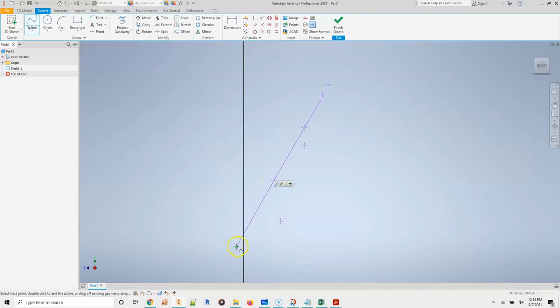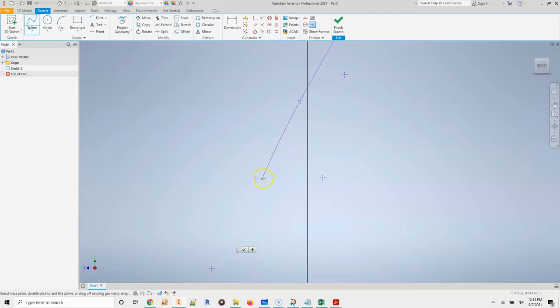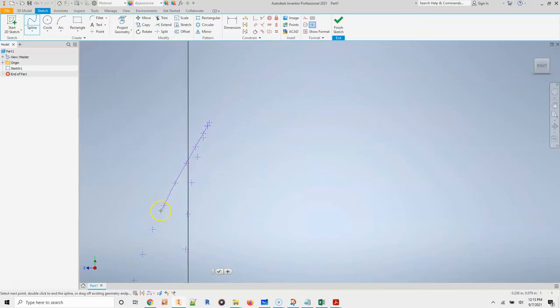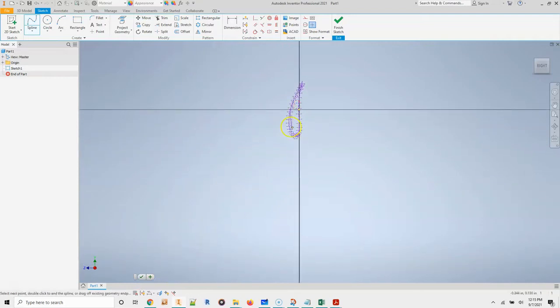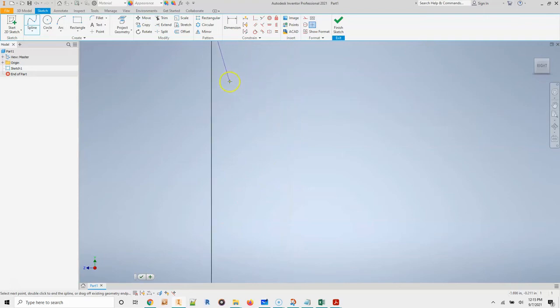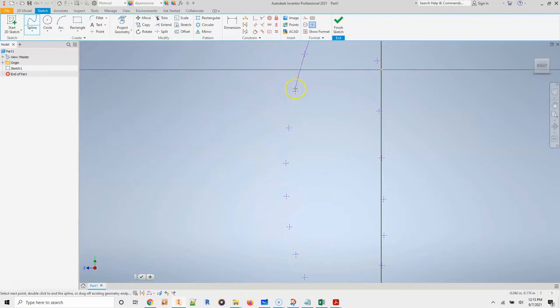So you're going to go across the top of the foil, push down on center click, and then you can drag the whole screen around. Click on more points. And if you scroll toward yourself, it zooms in. If you scroll away from yourself, it zooms out. So like right now, I want to zoom out, center click and drag, zoom in a little bit. I went the wrong way. Here we go, zoom in a little more, roll toward me.